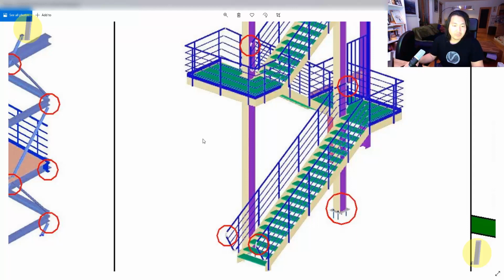So let's say, if your column looks like that, and if there's any steel connection completely inside of your column, of course in this case it's definitely an issue. So you can define that rule to report this as a collision, or like some element within another element, then you can report it as an issue, or something completely duplicated. So if you have exactly the same elements duplicated inside each other, then this kind of report you can make.